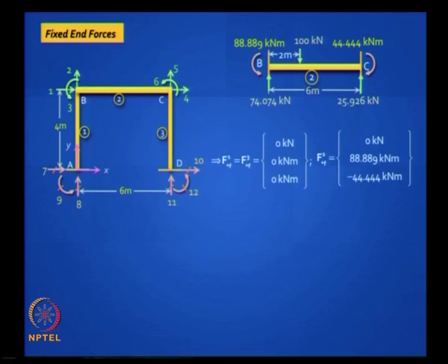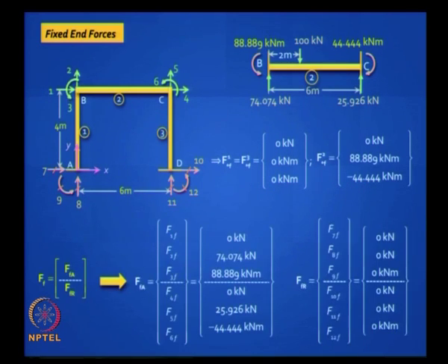Now we take this element alone has non-zero fixed end force vectors, and when you want to put it onto that structure you have to do it by inspection. This is a shortcut method. Reduce element stiffness method, you can't do TD transpose and get it. So doesn't it make sense to write down your fixed end force vector like this, because what are the contributions from the 3 elements? The first and third elements have no contribution, right?